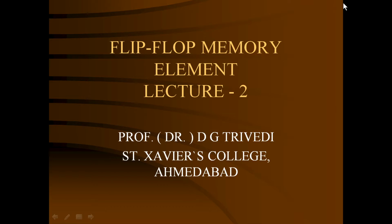Then the last condition is the forbidden condition. That is R is equal to 1, S is equal to 1. Both the outputs will be in the same state, Q is equal to Q bar. Hence, in a truth table, the output is going to be a question mark. That means it is a forbidden condition and it is decided not to impose this condition.